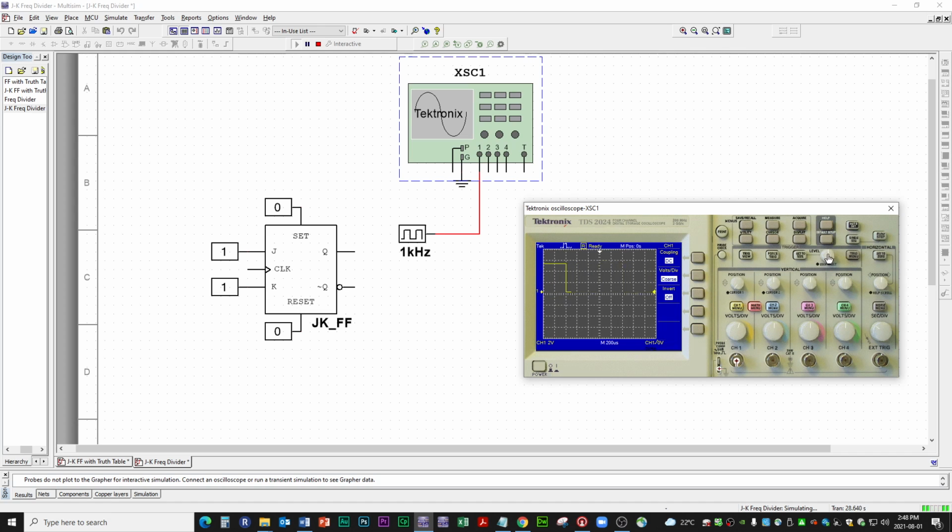We're going to change the trigger level. Let's call up the trigger menu. All right, so trigger is the edge, so it's recognizing the edge of the signal, rising edge. Mode automatic, it's not normal, so it's auto, so that's fine. It's automatically recognizing the signal.